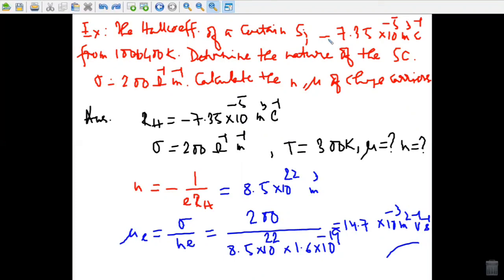So to conclude the semiconducting properties of materials, as far as our UG syllabus is concerned, the first point for semiconductor is that at ambient temperature, the free intrinsic charge carrier concentration Ni is very small and increases rapidly with the temperature. On the other hand, the density of majority charge carriers in an N-type semiconductor, Nn, nearly equals Nd, and in a P-type semiconductor, Pp nearly equals Na, the density of impurity donor or acceptor atoms respectively.